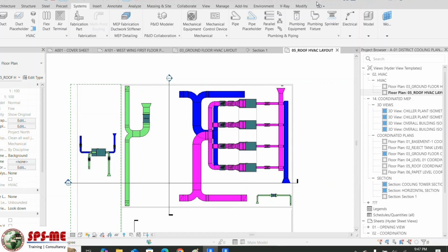Project management software. But we have another software called Synchro. We have the Excel Manager. So these software we will be using for the 4D. Okay. So when you connect your 3D model, that means you created your BIM model here, then that BIM model you connected with the plan, I mean Primavera or MS Project or whatever. Okay. The plan, then we call it as a 4D. Okay. And if you connect with cost, then we will call it as a 5D.